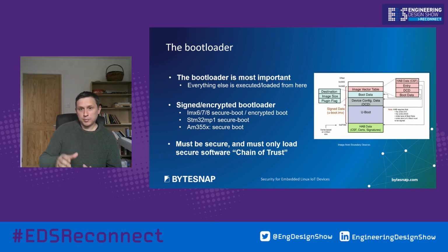It normally works through public key cryptography, which is where you use a private key to sign a piece of software, and then you can use the public key to check against it. And the public key will be programmed onto the device from the factory. And that means that any other bootloader that's loaded on there that hasn't been signed with your private key won't run.